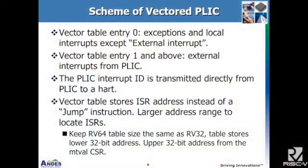On the other hand, it's very easy to extend the number of interrupt sources in the PLIC. So we think vectoring the PLIC is more scalable and systematic. It's a better solution, and it also works on multi-core. The scheme of our vectored PLIC is introduced briefly here. Vector table entry 0 includes the exceptions and local interrupts except the external interrupt. The external interrupt is connected to the PLIC, and vector table entry 1 and above will be used by the external interrupts from the PLIC.